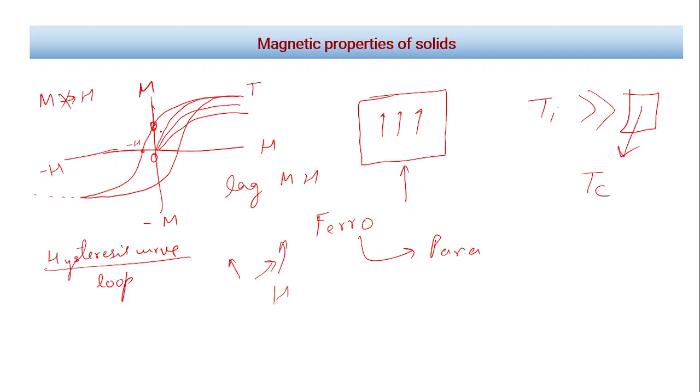Okay, and this is called retained magnetization, remanence. This is called saturation because the magnetization of the material becomes maximum. At this point, all the magnetic moments are aligned along the direction of the applied field, and then when we bring it back to 0, again they start randomizing, but still not completely random, and thus there is still some net magnetic moment even when the field is 0.